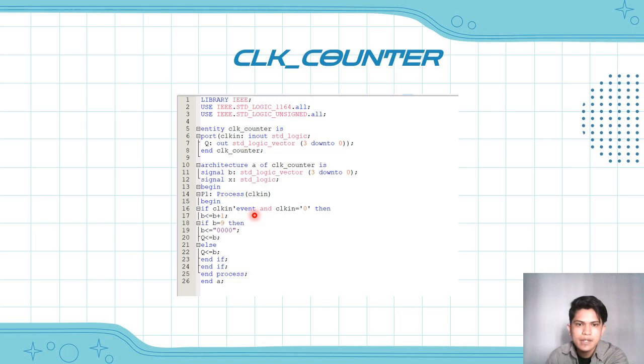After that, it has another if-else statement which checks if the value of B is equal to 9. And then if it was true, then the value of B is set to 0000, and it assigns the value of B to Q, the output port. And then if the value of B is not equal to 9, it assigns the value of B to Q directly.